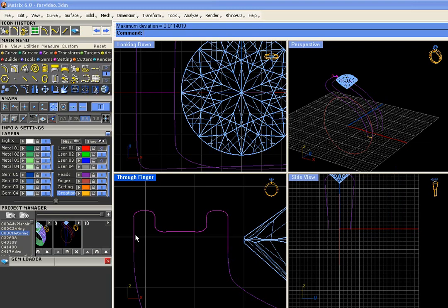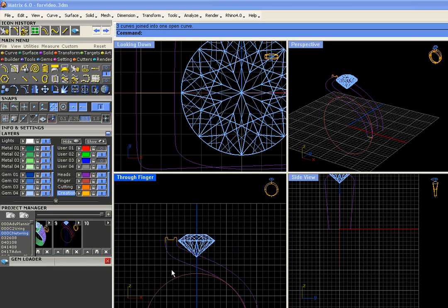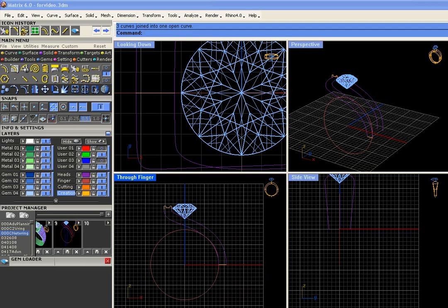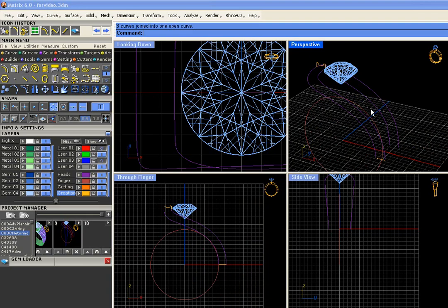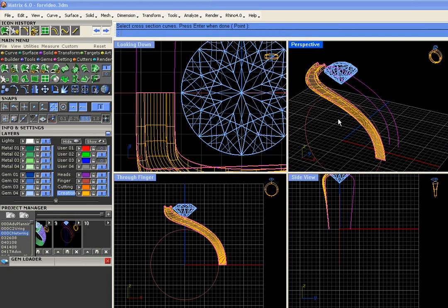And now we can join up the sides, but you want these to be separate from the top here. That's an important step. Okay, join these up. Good. Now we have a profile at the top and a profile on the side to sweep to. So let's go ahead and run sweep to between the two rails and the two profiles. Okay, that creates a pretty neat shape.